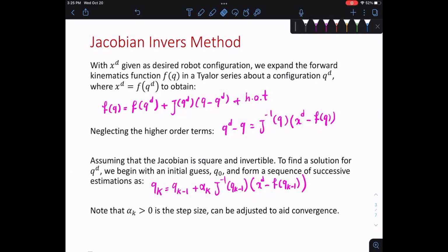And remember, the Jacobian was a mapping of how your joint values will affect your point position. So you multiply by that. Now step 0, your initial guess: you can set all of them to 0, or you can say, I think it's like 30 degrees and 60. You plug in theta 1, theta 2 as 30 and 60, calculate this value, and you see that my second estimate is going to be that. And then you're checking against your actual desired position.